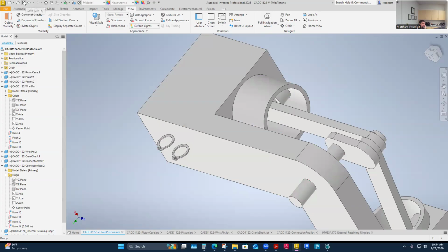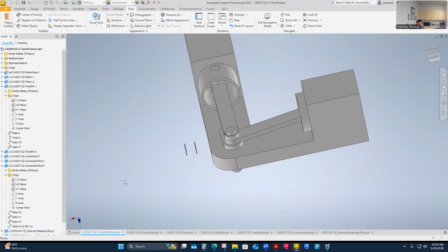So I'm going to continue on and keep recording today because I'm just going to plow through. Tomorrow I'm going to start doing my drawings. Each part has to be put on that drawing template. When I do that, it's going to be the whole assembly on one, and I'll show you how to do a parts list and a BOM for it. And then we'll break down these parts and dimension them like we would AutoCAD drawings: three views, isometric view, start dimensioning these out, place center lines on it, do the whole ASME nine yards on dimensioning.